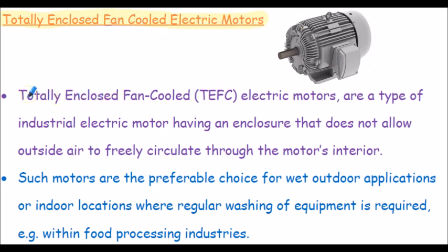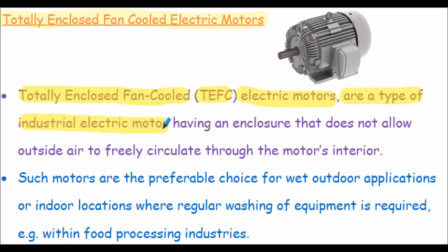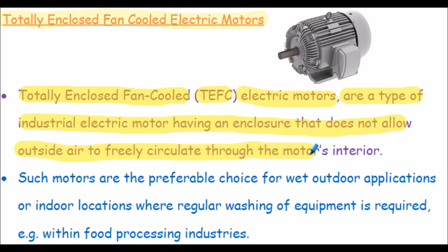So totally enclosed fan-cooled motors, acronym TEFC, electric motors, illustration shown here at the top of the slide, are a type of industrial motor having an enclosure that does not allow outside air to freely circulate through the motor's interior.